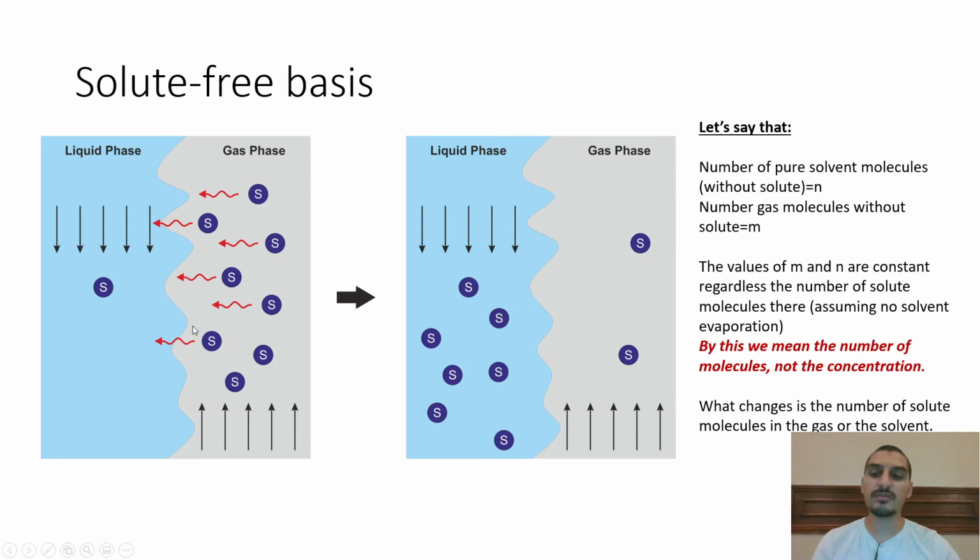That if I have 100 moles of the solvent going in and they come out as 105, they are actually 100 as they were in the beginning, plus the 5 moles that they gained from the gas phase. And the same here. If this is 100, it's actually 95 plus 5, so it's losing 5 and the rest is 95, which were the 95 that I started with from the very beginning.